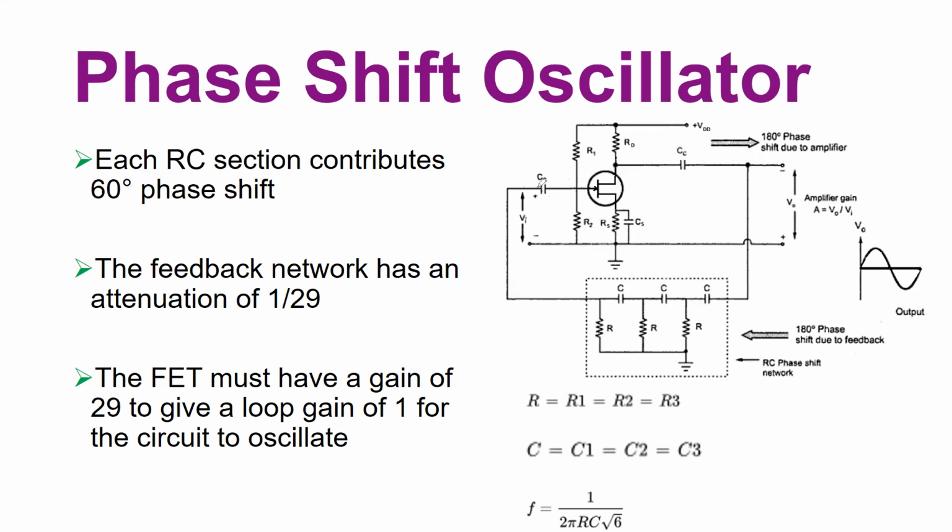Depending on the frequency range, you have to select their values in such a way that for the entire frequency range, they act as a short circuit, coupling the AC input to the circuit and the AC output to the load. And R1 and R2 are used for biasing to provide the operating point here. The operating point, not the stability; stability is provided by this resistor.